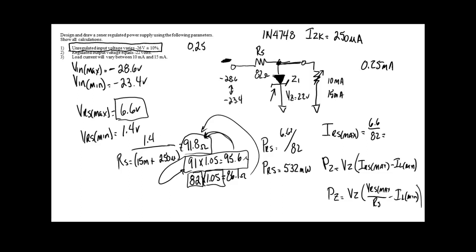We gotta calculate the power of the resistor. Now, I know I told you about the power supply class I taught, right? Where they kept burning up 100 ohm resistors. And they came up and kept blaming it on something's wrong with my power supply. It keeps burning up these resistors. But what they did is they just got a little old quarter watt, 100 ohm resistor, and they was putting it across a 30 volt power supply. And what would that be?